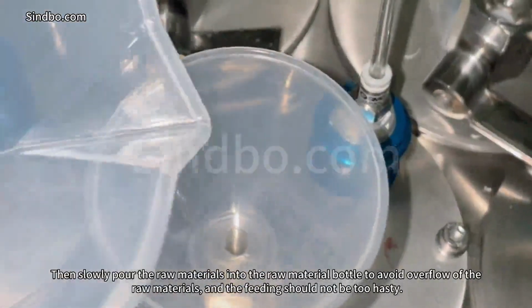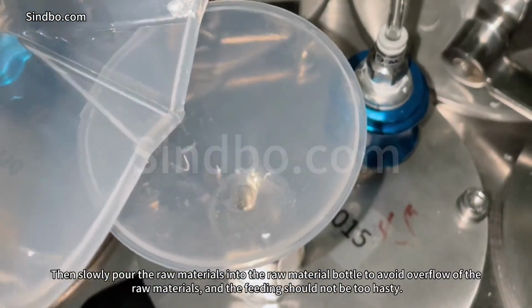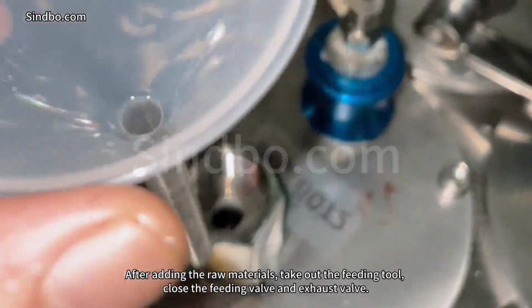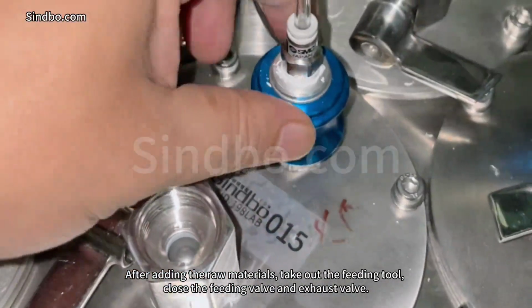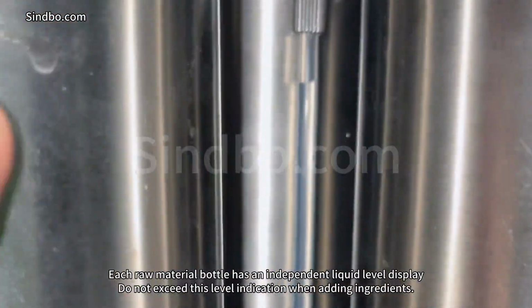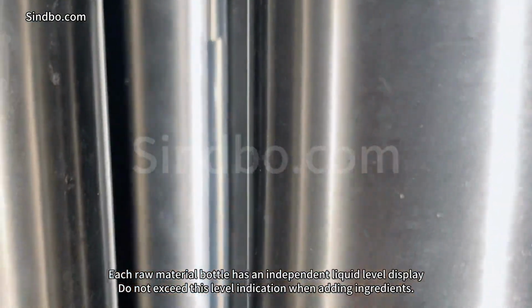Then slowly pour the raw materials into the raw material bottle to avoid overflow, and the feeding should not be too hasty. After adding the raw materials, take out the feeding tool, close the feeding valve and the exhaust valve. Each raw material bottle has an independent liquid level display. Do not exceed this level indication when adding ingredients.